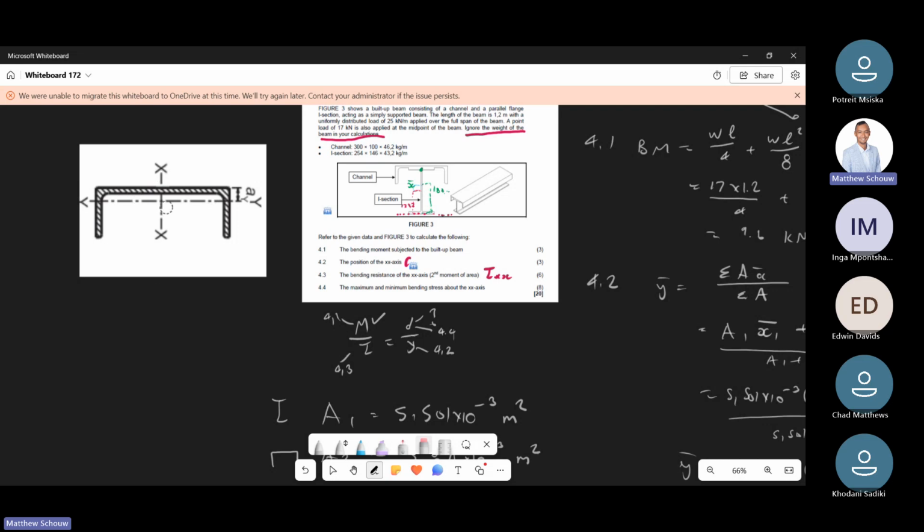So you must be careful depending on how it's orientated. You're bending across this axis, not that axis. Bending is happening over here, so you must be careful. The value they give you, Ixx, is like this. That's assuming you're bending that way over. But our channel is not standing up vertically, it's laying down on its legs, the flanges, like that. So it's bending that way over, which means we must take Iyy. Does everyone get that?